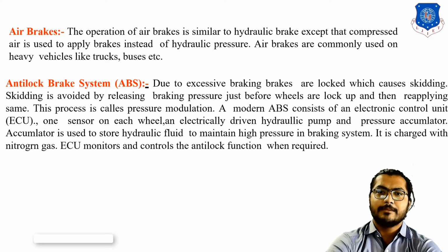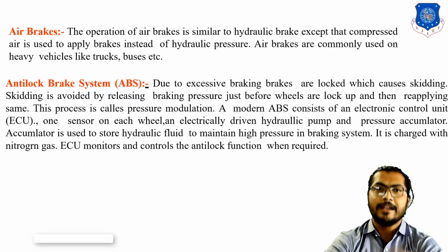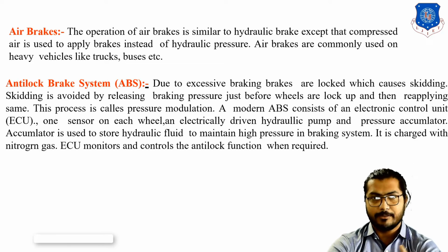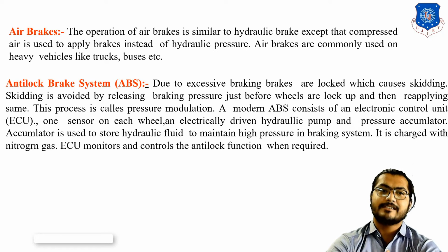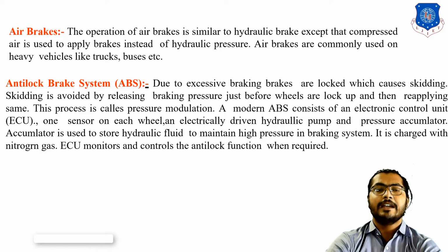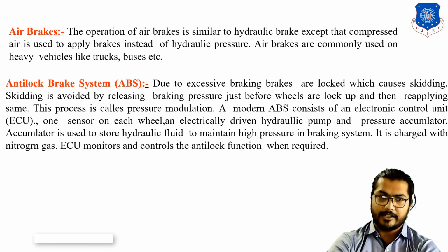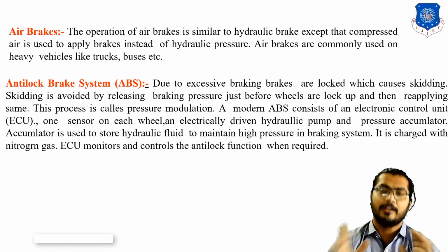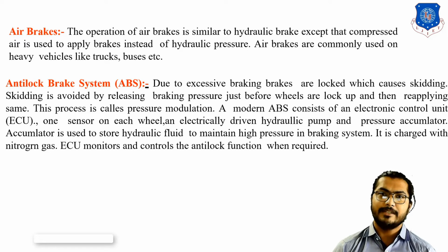Okay, next is the air brakes. Air brake is a similar type of braking system, exactly the same as the hydraulic braking system. But in the hydraulic braking system, we use hydraulic fluid. In this braking system, air is used, like compressed air is used to apply the brake instead of hydraulic fluid. Air brakes are used in trucks or heavy loaded vehicles, like trucks and buses. In those vehicles, the air braking system is used.